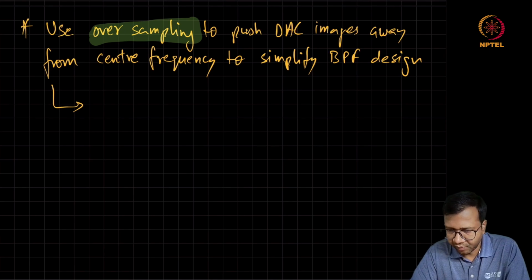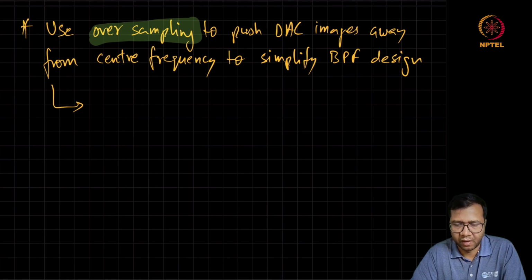It still requires some tunable analog components, which dilutes the overall motivation of using an RF-DAC. So the idea was that we can just give a digital input and generate an RF output. And in between, we were able to get rid of the anti-imaging filter at the baseband. But now we are just pushing that filter into the RF domain, which is not exactly simplifying the overall chain.